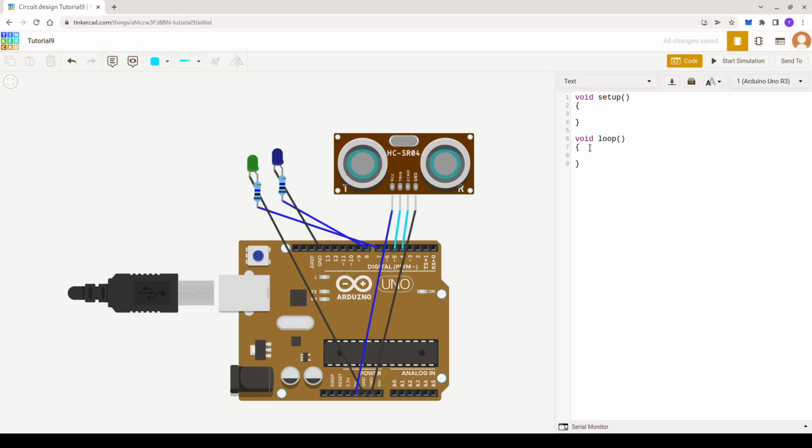input. Okay, guys. So let me just do the pin mode very quickly for all of you. So pin mode. Over here, first let's do the LED one. So 8 to output. As we all know, the 8th pin is the red one. Now just copy paste this several times, because I don't want to type much. You don't want to type the same again and again. That's boring. So 8, 7.